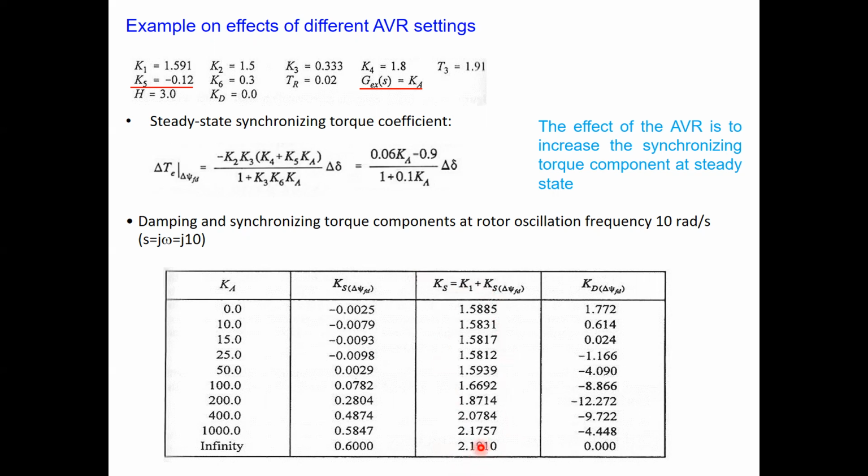Now, if you take the total torque, right? Total torque in this case is 1.585 plus 1.772. Agreed? Then for this case, it is this quantity. For this case, it is this. But if you have a gain of this value, then the total torque will be 1.5812 and the difference of this quantity, right? So that means for a higher gain setting, the electromagnetic torque reduces, the net torque reduces, because the damping factor becomes negative for a higher gain factor here. This is what it reflects here.